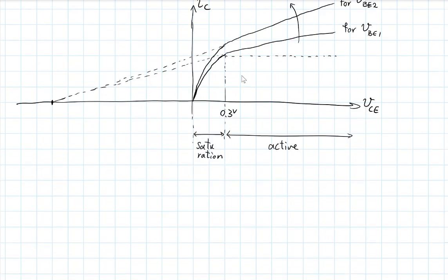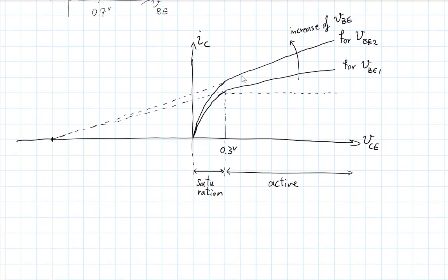It's not an ideal current source. It's a current source whose current is, to some degree, you might say, almost constant with the voltage, but not quite. And now, if I wanted to model the circuit, rather than an ideal current source to represent that mode, what should I do? Is there something else I could include to capture the fact that there is a slope there? That slope is telling me that by increasing VCE, IC, even in the active mode, is not constant. It's increasing slowly. How should I capture that?